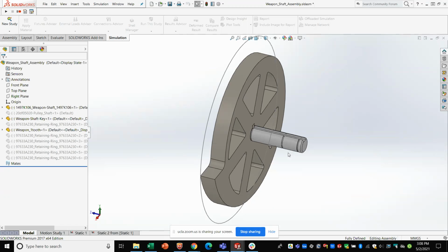If you were welding two parts together, for example, you could use bonded contact. Now, you would need to make sure that they were only bonded along an edge where the actual weld bead is, but that's neither here nor there. You can use no penetration in cases where you need more realistic results, and you can combine no penetration with forces that keep the two parts mated together, and deal with the associated computational slowdowns if you have to.